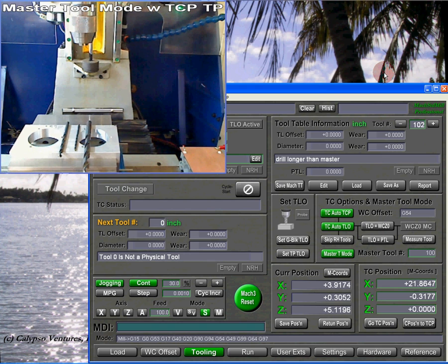is master tool. Now what I'm showing you is that I've got a drill chuck mounted in the machine, and I'm going to use the drill chuck for all three of these drills. So we will treat all three of these as if they were in non-repeatable height holders, i.e. the chuck doesn't necessarily make the drill the exact same length each time you mount it. I'm going to use the middle length drill as my master tool, arbitrarily. That will give me a tool which is shorter than the master and a tool which is longer than the master as I go through this demonstration.